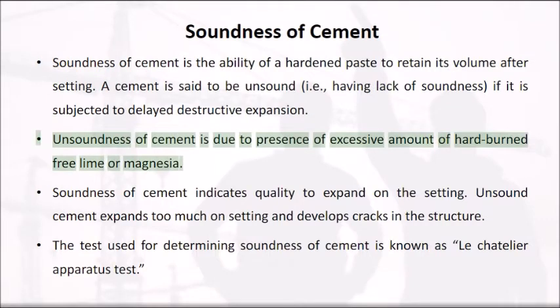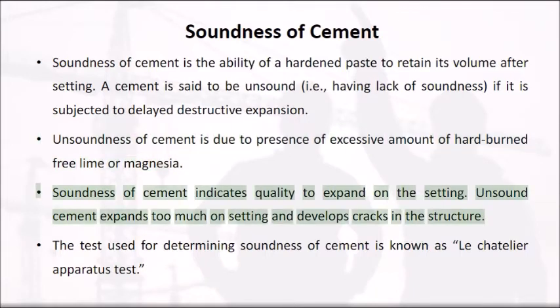Unsoundness of cement is due to the presence of an excessive amount of hard burned free lime or magnesia. Soundness of cement indicates its quality to expand on setting. Unsound cement expands too much on setting and develops cracks in the structure.